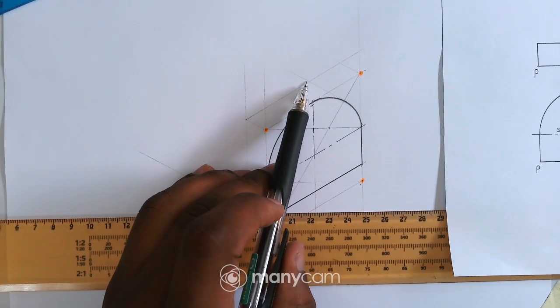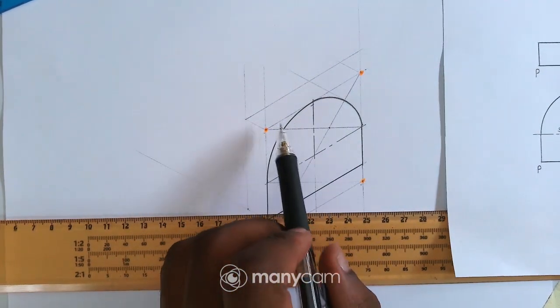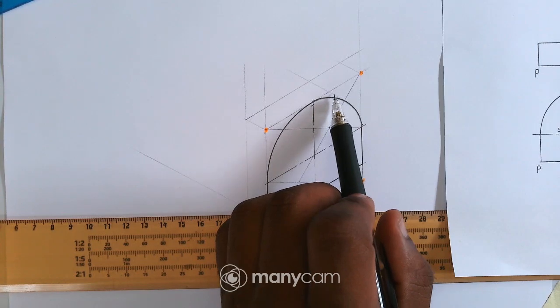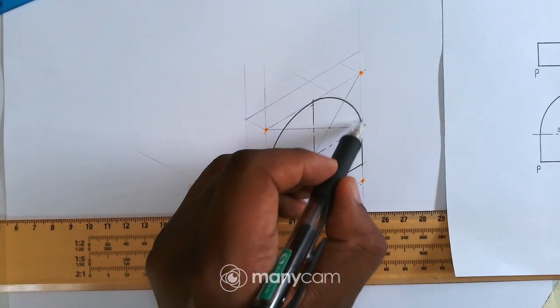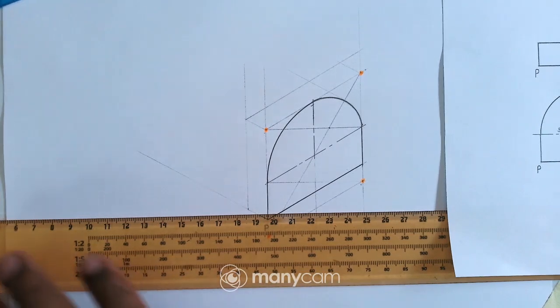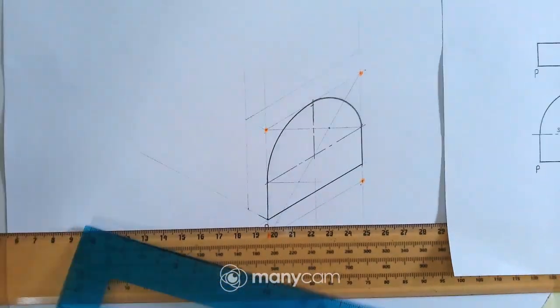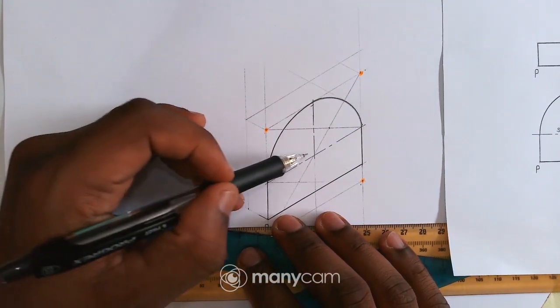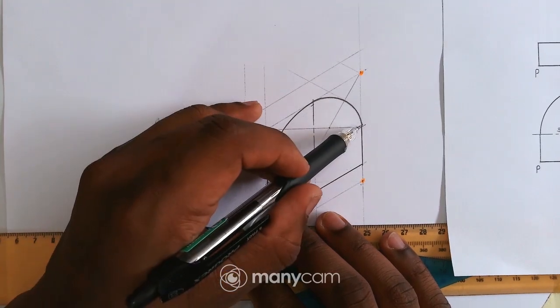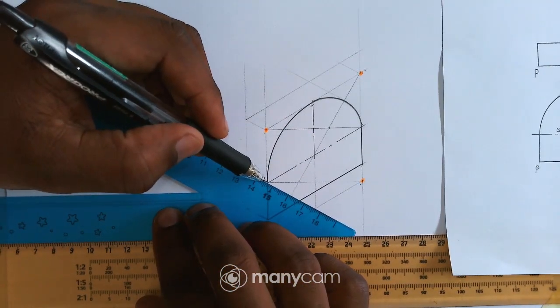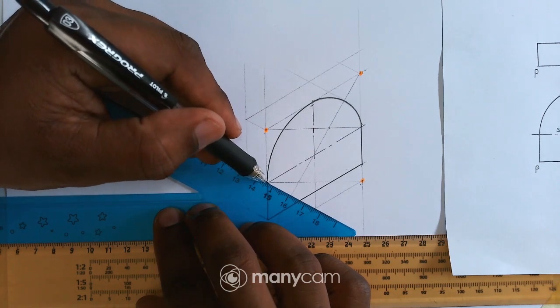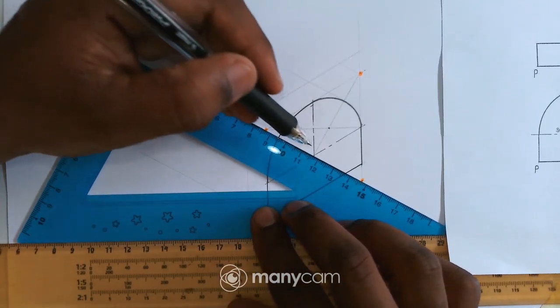It's because obviously when I draw the arc, I must end on this line. I cannot draw a complete arc just like this one, but you see as I proceed. So now what I have to do is project these points up for the width of the object. So I can project this point up, the center point as well,